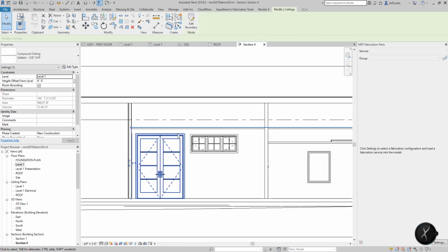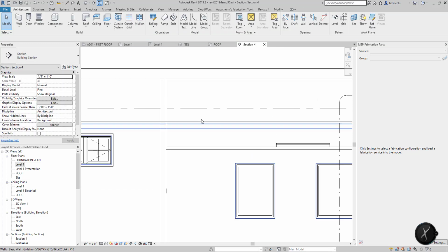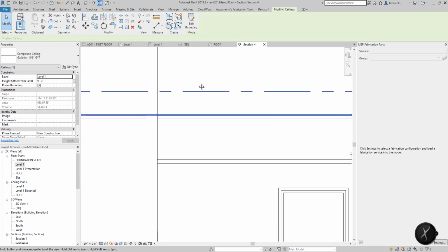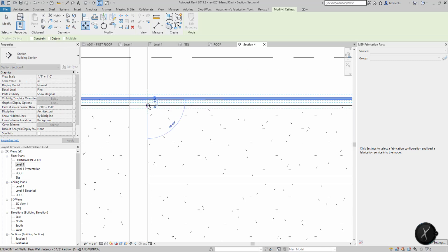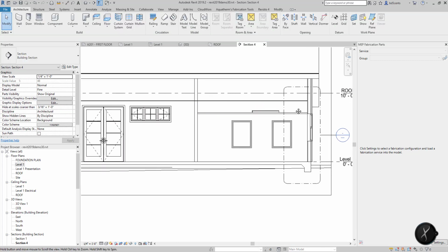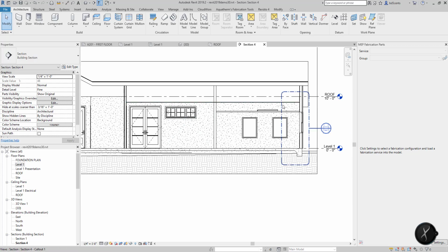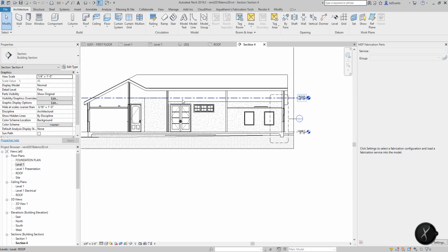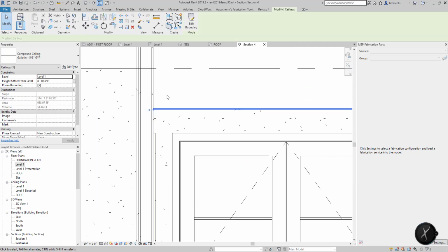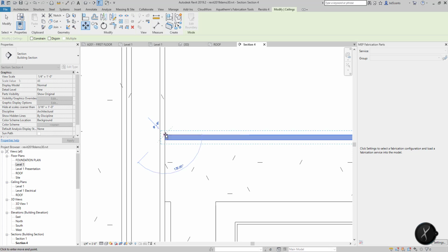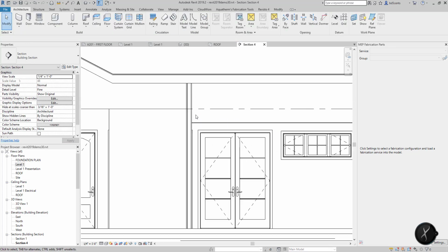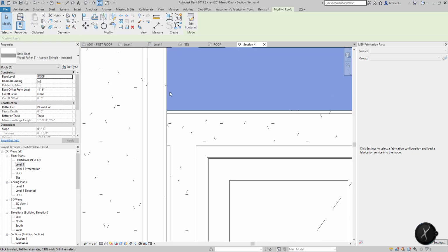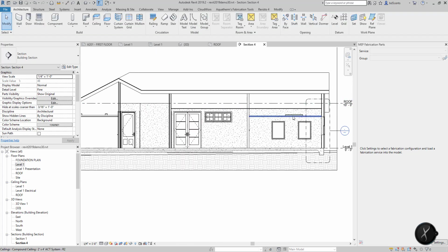Let's go ahead and pop that up to 9 feet for now. And we can actually move it to adjust to the same height as this roof. So we're going to move it down to adjust to that same height of the roof. So now I've got the ceiling in at the correct moment in which it touches the roof. Realistically though, because of the thickness of it, I would want this top line to be where the bottom line is, and that's lining up directly with the actual roof. So if I look at that, we're all good, everything's in place.